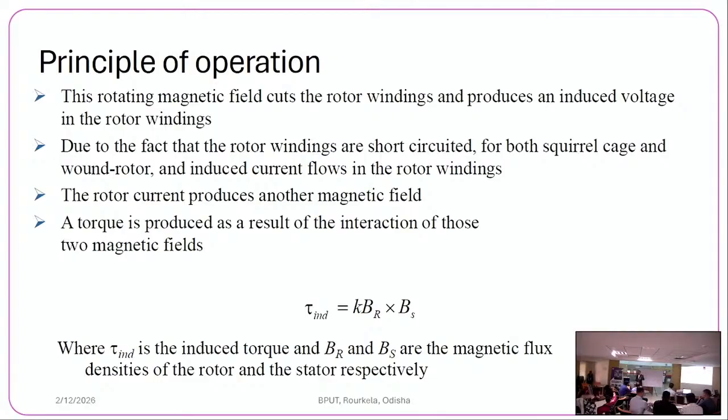Speed of the stator minus speed of the rotor is zero, that is synchronous speed. The speed reduces, but if the speed becomes zero, relative speed becomes zero. That means the rotor is also rotating at the synchronous speed, same as the stator. So relative speed will be zero, but then there will be no induction. Though the relative speed is zero, there will be no electrical induction.